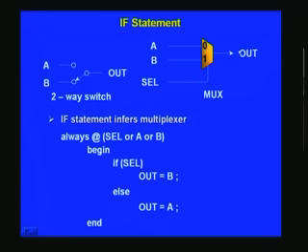And suppose you want the output here to be B. So, what should you have? Select must be 1 here, then only this B is selected. That is precisely what this statement means. If you do not put equal to 1, which you can also do, it implies that it is 1. So, that is a short notation, but I personally discourage this. You put double equal to, then 1 stroke B1, that will convey how many bits and all at one stroke.